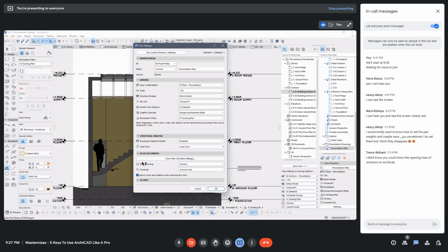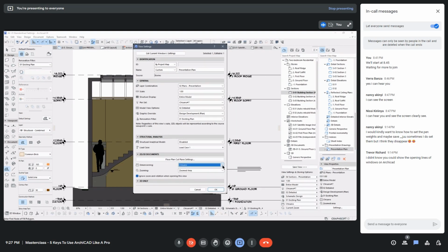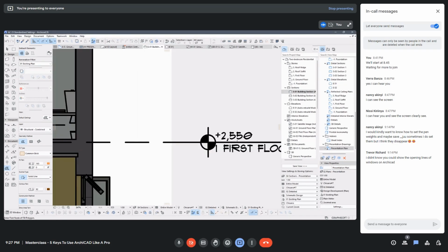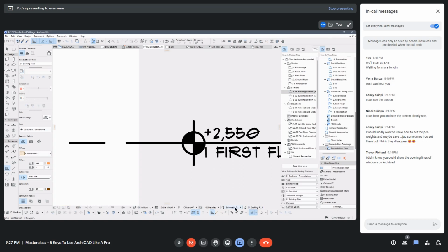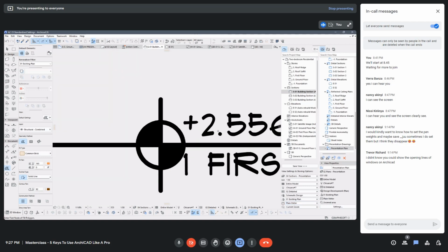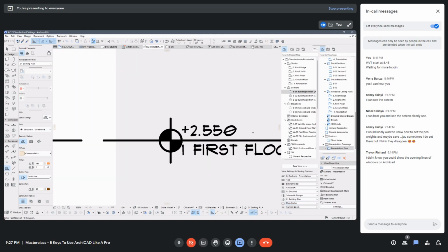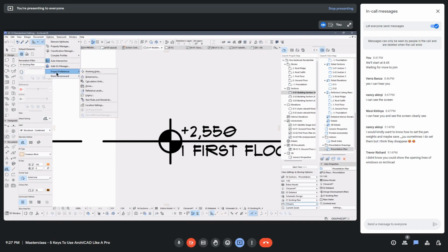Yeah, you also have the ability to change the dimensioning. Maybe you've worked sometimes and seen as you're working, these dimensions start showing with, let me just change this to this plane meter. You start seeing this dot 2.55. So that's basically telling you about the dimensioning preference, this project preference here. How you access that is by going to options, project preferences, dimensions.